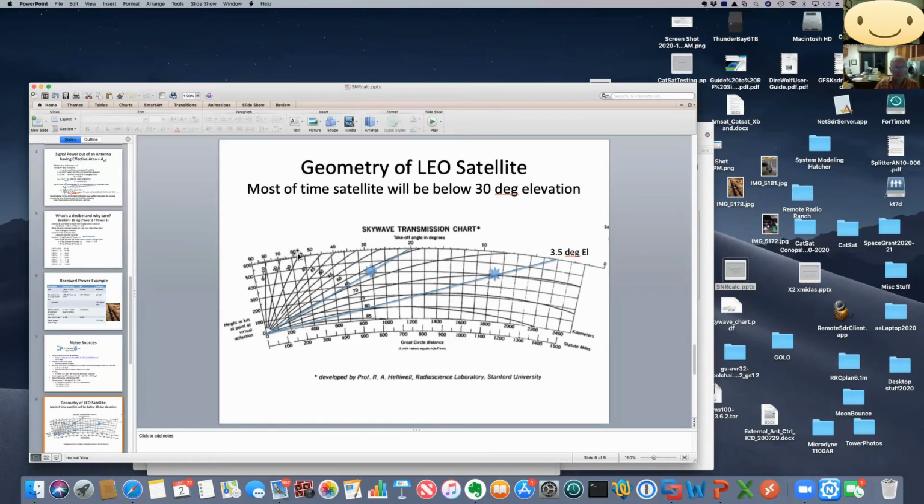So especially for these low orbit passes, you've got to run a bunch of your own orbits and see for yourself. But you're going to find that most of your passes will end up being at relatively low elevation out in this range, out in here. Very few will be near overhead.